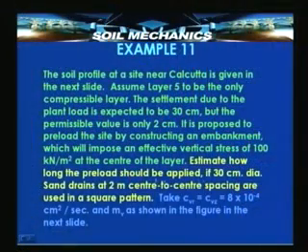Preload should be kept long enough to cause 28 centimeter settlement, and then once you remove the preload and replace it with the actual structure, there will only be a settlement of 2 centimeters, which is well within the permissible value and the capacity of the structure to adjust to the settlement. Now the question asked is, estimate how long the preload should be applied,